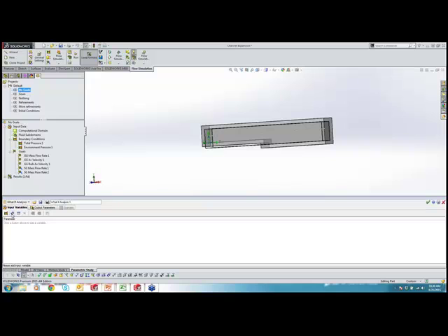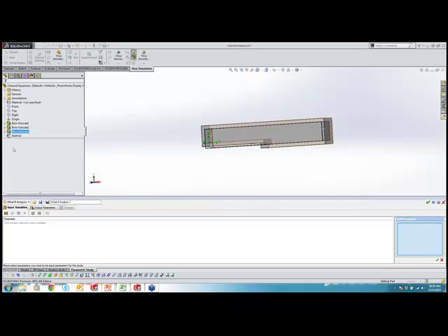You could set up an assembly with a mate of that piston moving inside of the valve, and then use this dimension parameter. You'd click on that mate in your mates if it was in an assembly, and it would add that parameter, and you can move the piston up and down inside of the valve, have it solve each one of the iterations so that you get an idea of what the flow field coming out of the valve looks like each time.